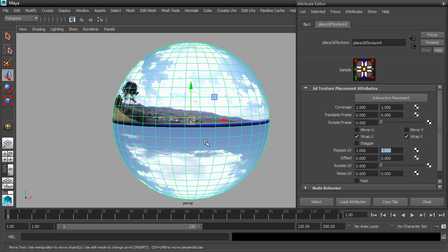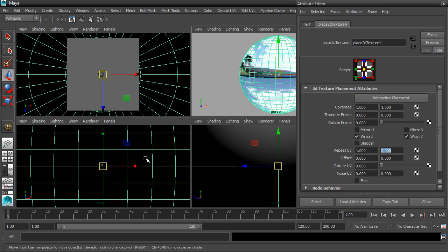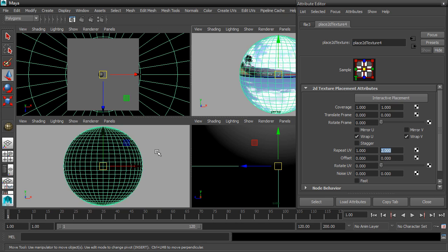Now we want to delete the bottom half of that sphere. Let's do that from the orthographic views. Tap the space bar, and in the front view, dolly out. And we could imagine that we could just simply delete the bottom half here, but there's something that may trick us here, which is that we're not quite sure where the positions of the orthographic cameras are, which means that we're not quite sure if we're going to select all of the polygons or not.